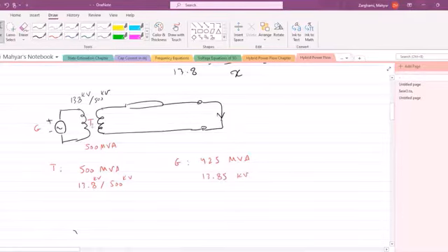If you have a 500 MVA transformer in here, it's bad practice to connect it to a generator that has a 10 MVA rating. So you're not utilizing the equipment in a wise and optimized way. The devices that are connected to one another should all be around the same rating. So 500, I would say, is comparable to 425 MVA power-wise.